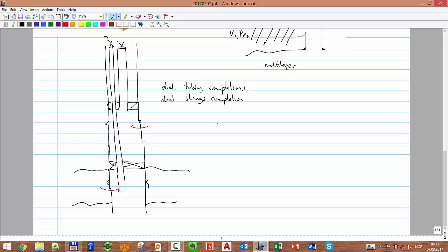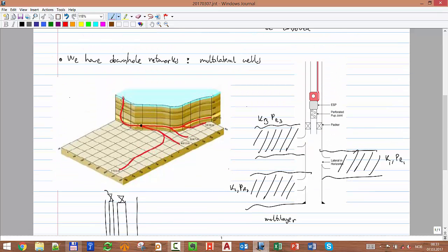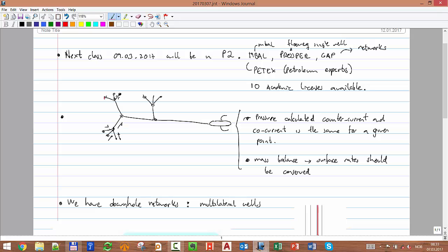And if I'm going to make a sketch, I can almost have it like two separate conduits, yeah? I can model it like that, like two separate conduits. While in this case, you see that the three of them reach the same place. And that creates some problems. Like I told you, when we have a network, it might be that that well is very strong, okay? That well is at a high reservoir pressure or has a high productivity index, and the well next to it might be very weak, yeah? It might have a low reservoir pressure, a low productivity index, and then you have the play that will try to produce more and that will produce less.